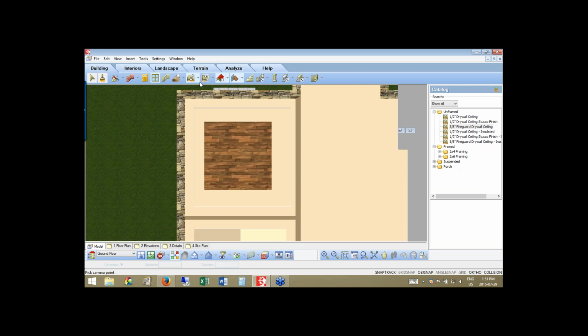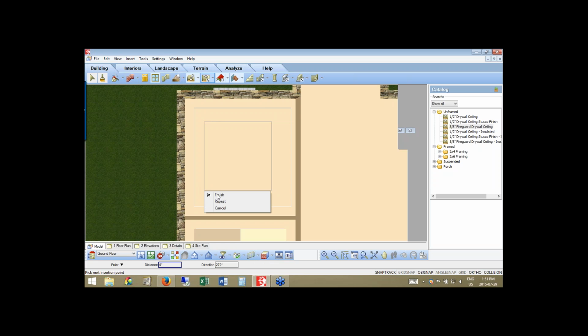So I'm going to pick on our ceiling tool again, ceiling by picking points. And by ceiling by picking points, now I can pick those corners of our ceiling and see how it's nicely snapping to it. I'm waiting for that circle with an X. It's filling in that new ceiling right there. Pick those 4 corners, right-click, tell it I'm finished. This ceiling, when it goes in, it's going to go at the same height as our original ceiling. So it's going to be at 8 feet.